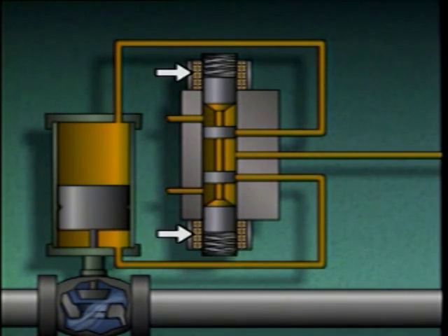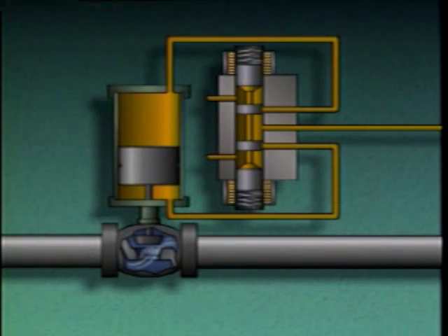The pilot valve is operated by the solenoids, or electrical coils, which respond to signals from a controller to position the spool. In this example, one solenoid is attached to the top of the spool, and one is attached to the bottom of the spool. When both solenoids are de-energized, the springs return the spool to a neutral or centered position.